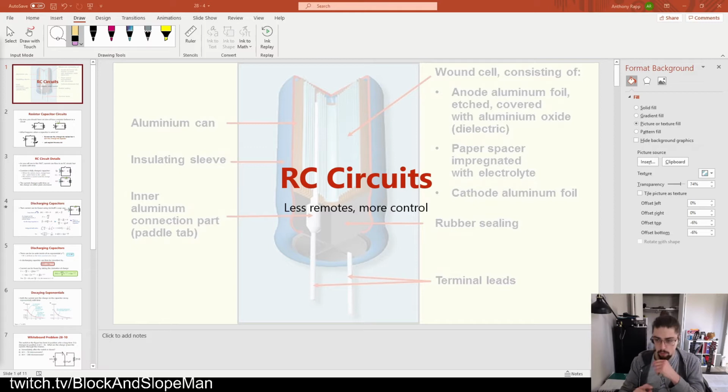Sometimes they are coiled up plates. Sometimes you'll see what we've got in our background picture right here, where it's fins that are laid on top of each other. I've got a fin that has one charge, and then there's an electrolyte infused paper acting as the dielectric in between. And then your other plate. And the entire reason, remember, that we had dielectrics in the first place was to increase the capacitance so that it was a reasonable size, right? It's this and not the size of my notebook to get effectively the same capacitance. So, today, we're exploring those a little bit more.